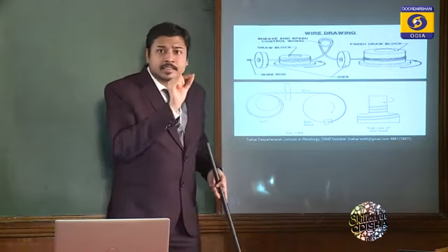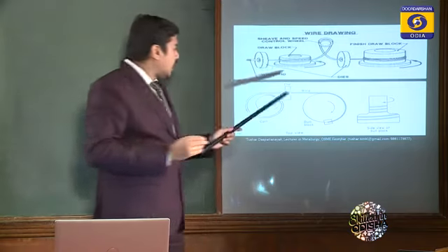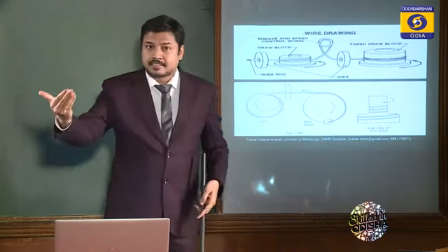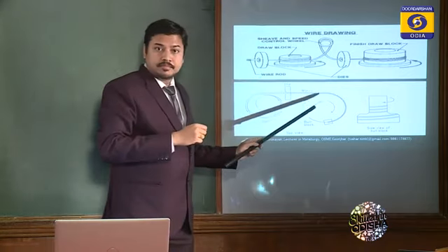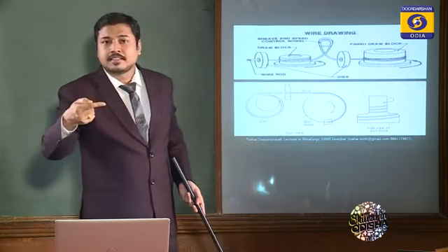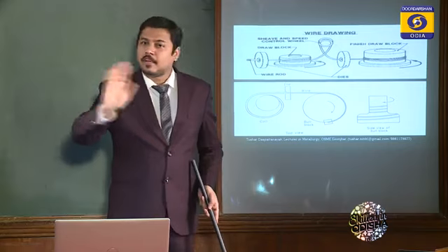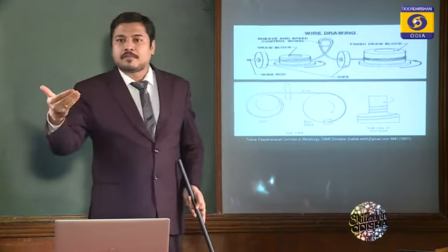So it has to be successively reduced. It has to be stepwise reduced. I have to use 3-4 dies or 3-4 systems. 6 mm to 5 mm, one coil, then 5 mm to 4 mm, one system, 4 mm to 3 mm, one system, 3 mm to 2 mm, 2 mm to 1 mm, 1 mm to 0.5 mm.